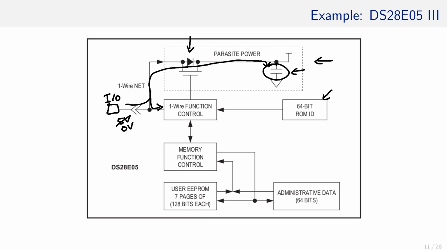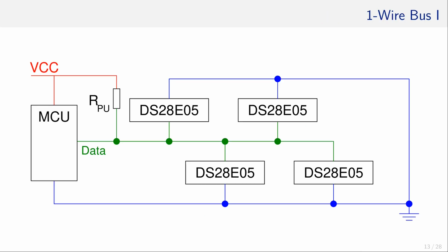What about multiple devices? A major difference that I mentioned earlier when comparing with the DHT protocol. In this session, we talk about how one-wire devices communicate. The one-wire is a bus and allows multiple devices, such as the EEPROM mentioned previously, to communicate and to draw power from a single line as shown in this figure in green.